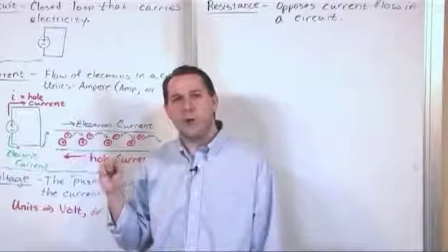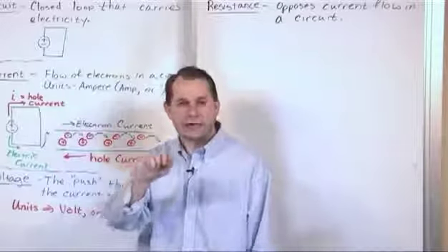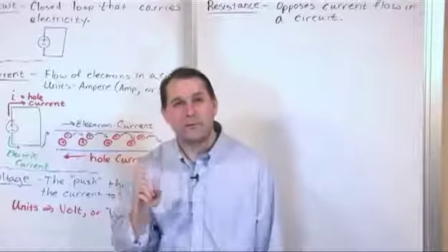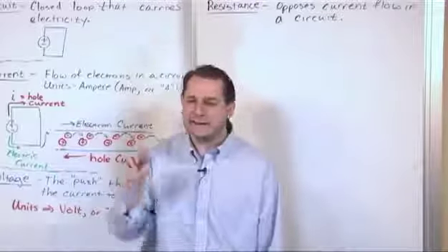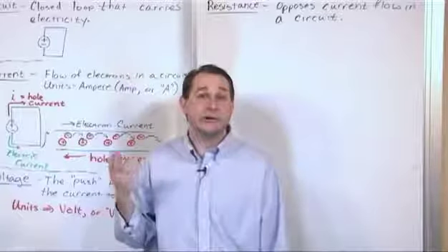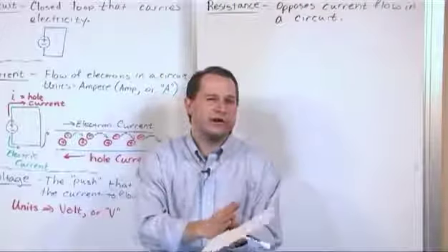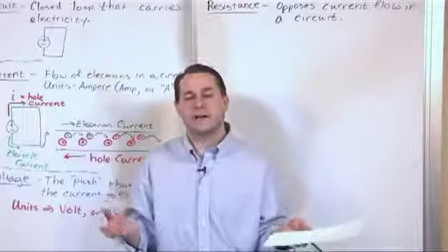But if I get a wire thinner than my hair, or a tiny wire etched onto a computer circuit chip, which are so small that you need a microscope to see them, then the cross-section of a teeny tiny wire like that is going to be so small, it's going to actually resist the current. The electricity is going to move through there, but it's going to cause friction. There are just not as many atoms there for it to move. So the resistance is going to be higher.